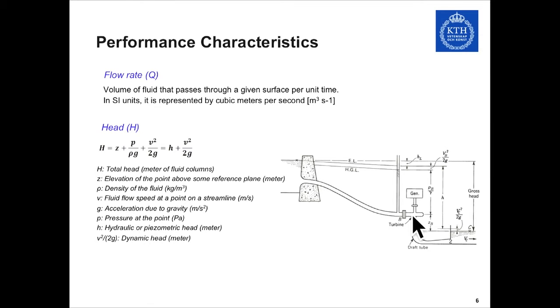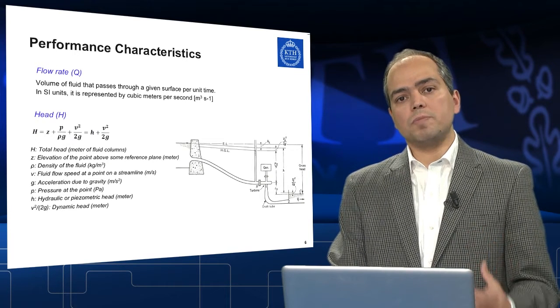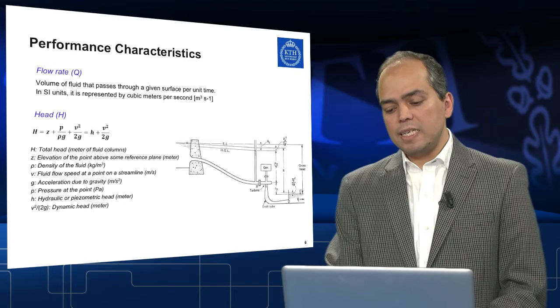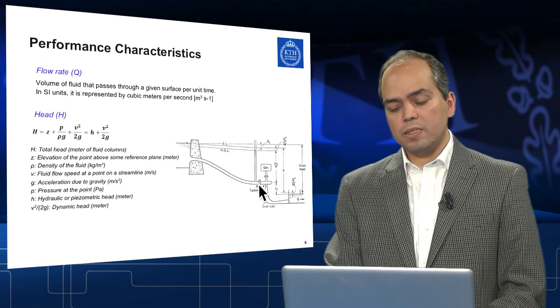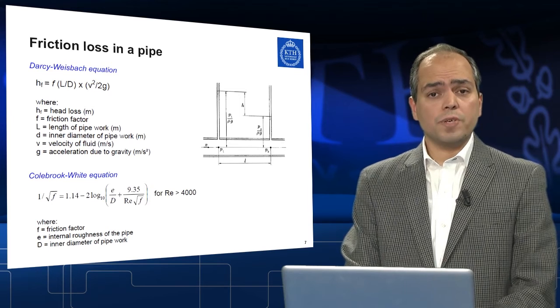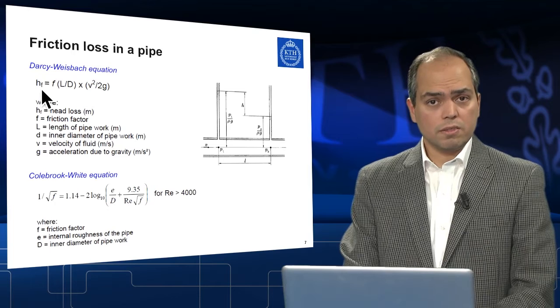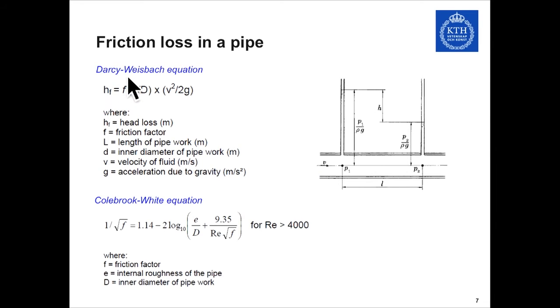In the previous equation that we've seen, the H, in order to calculate the power from hydropower, is in fact related to the head differences between the inlet and the tail level. In order to calculate the available head here, one should calculate the pressure losses in the system. And you've seen before in the first series of lectures by Brijesh how to calculate the head losses in your system, which is through the Darcy-Weisbach equation.